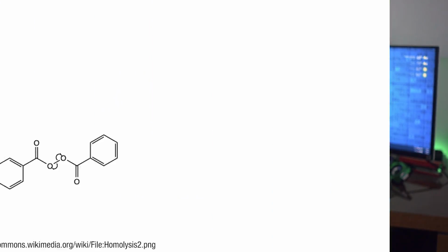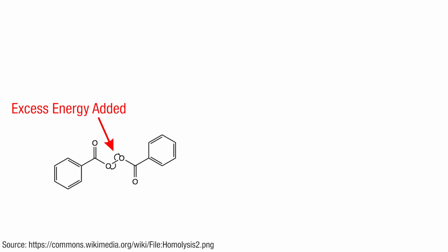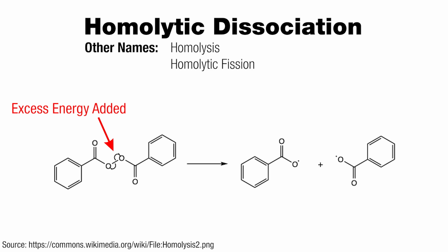Basically, there is a very small chance for an electron to collide with another atom's electrons and cause it to have such a high energy level that it actually breaks an atomic bond completely. This is called homolytic dissociation and results in atoms or fragments of molecules being separated into what are called radicals, which basically end up being defects in the structure of the panel at the molecular level. The more of these radicals, the more they interfere with the electrons around them, causing even more kinds of non-radiative recombination. Therefore, this ends up decreasing the efficiency of the panels over time.